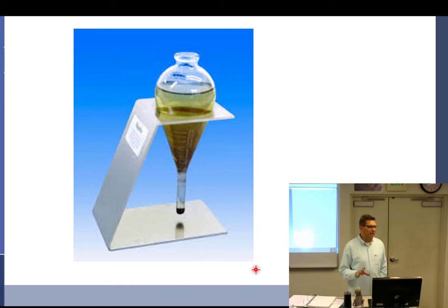That's all part of the NDT process. And like we've already learned from day one, that's part of what a Level 1 should be able to do: turn on and calibrate the machine, make sure everything's going. So one of the things you always have to do, especially with a wet bath that's open, is what? According to the picture, concentration. I've got to check my bath concentration every day.